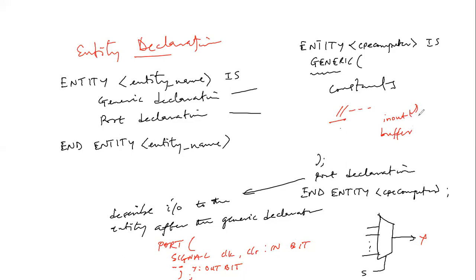While buffer is for output with internal feedback. So you really don't want to use that, except there's a special use, you are so certain you need that in your design. So you now see that, fine, this is the hardware we want to achieve, but using your VHDL coding, we could put this up as code, and then voila, we get what we are doing.